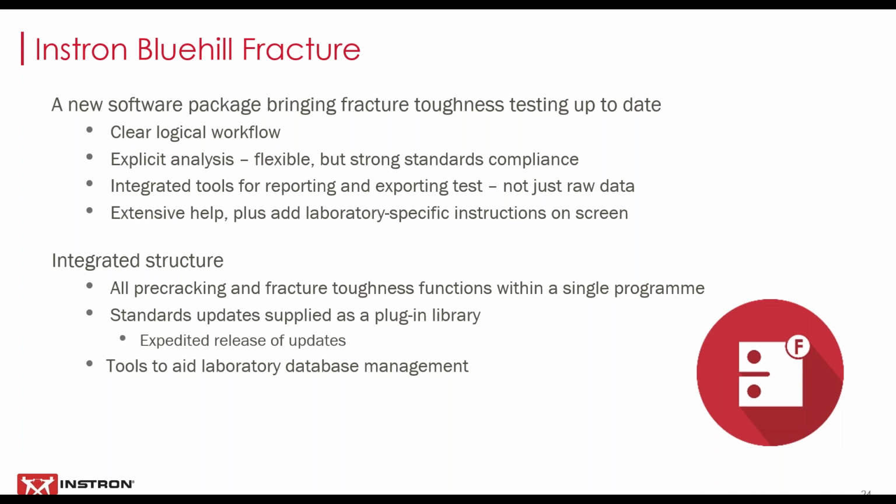And the integration side of things is bringing all the parts of the test together, about pre-cracking and fracture toughness measurement, within a single program, rather than doing one stage and then doing another stage. Bringing standards updates in easily and integrating with data management systems within the laboratory.